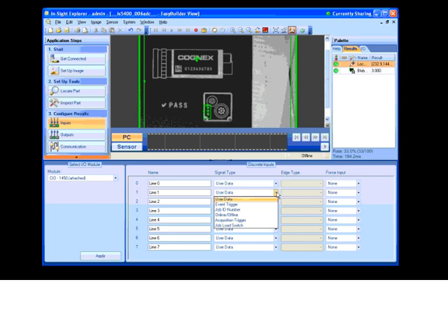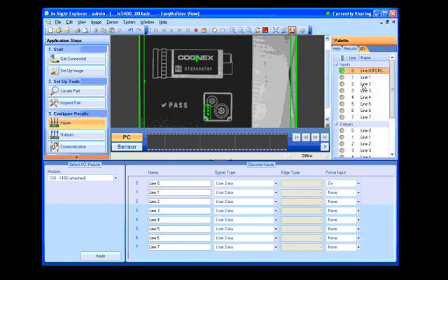We can also set up line 0 or line 1 here to look for an acquisition trigger, in other words, to trigger it from like a photo eye, functionality like that. And we can also do this online, offline, functionality there. We can force our onlines high and look at our functionality over here in an I/O tab. Yes, I have forced it to go high. Turn it off, and it is grayed out.